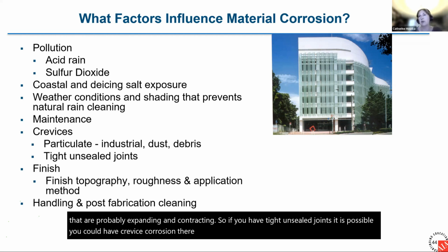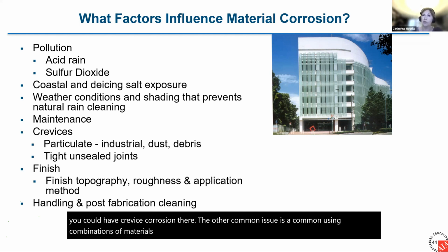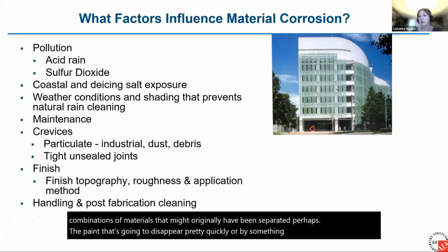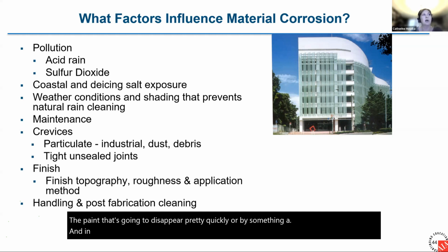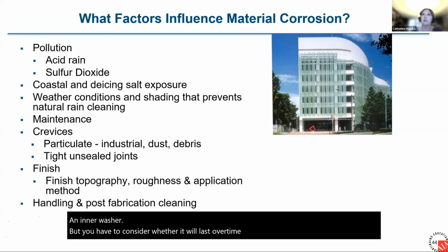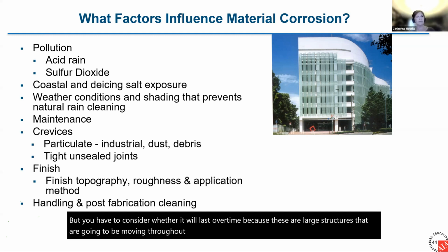The other common issue is using combinations of materials that might originally have been separated, perhaps by paint that's going to disappear pretty quickly, or by an inert washer. But you have to consider whether it will last over time because these are large structures that are going to be moving throughout the day.